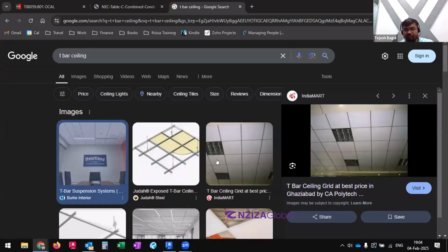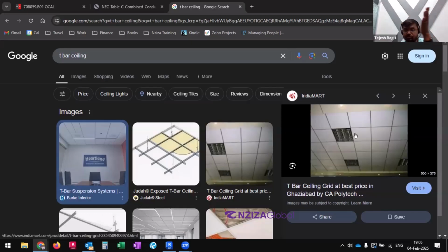After this one, if you count 2 tiles, there will be another light fixture over there. So keeping it aesthetically pleasing will be one of the biggest things, but make sure that the path you are choosing for the path of egress has light fixtures on it or close by.